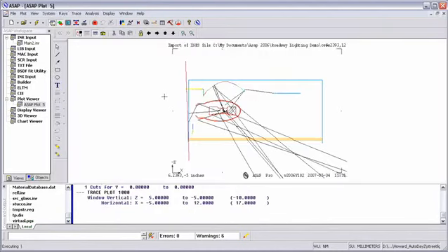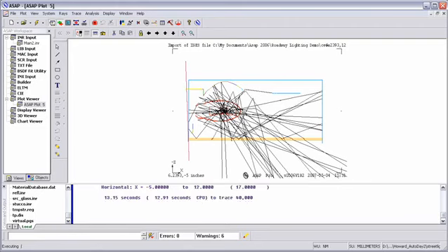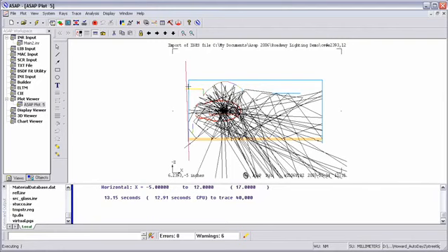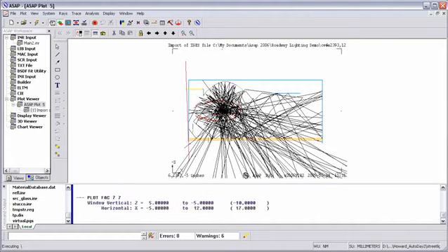Okay, the first thing that you're going to see on the screen is the simulation of the actual architectural luminaire. So we have the HID source with the geometry included, and in cross section you can see the reflector that's been designed for this particular case, and then we have the housing and the glass and the pole that's holding the part. In the plot that you see before you, we're tracing a limited number of rays to the screen. We're actually tracing more rays to simulate the output, and we're limiting the rays on the screen in order to keep the screen clear.